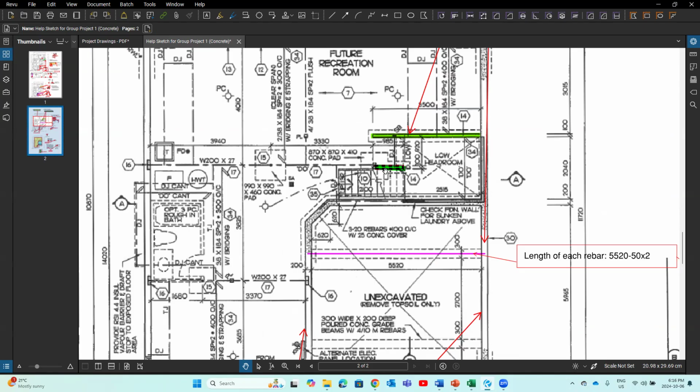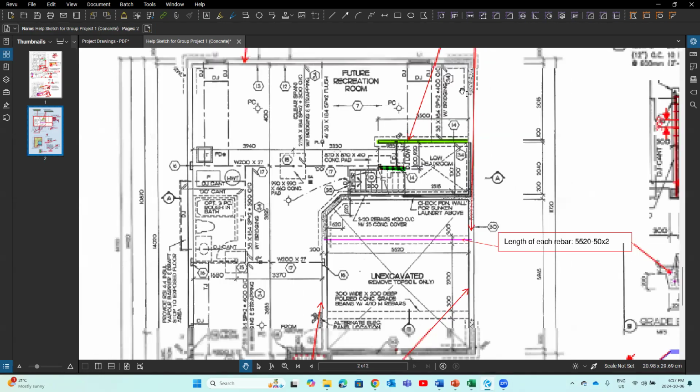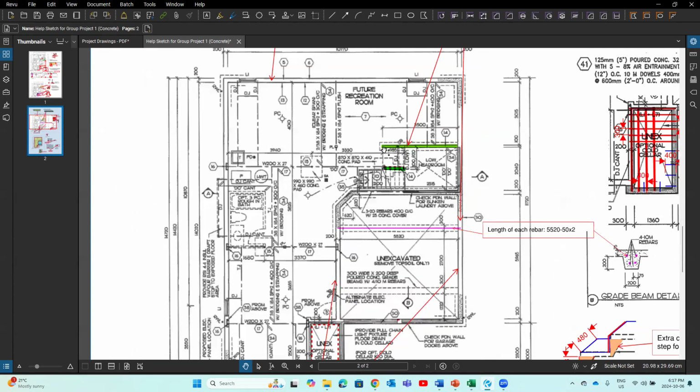That's a spacing of the anchor bolts, right? If we take the total length divided by that spacing, we don't have enough for this kind of situation, right? So what do we say? Each open end, we also add one extra anchor bolt in our estimate. That will give us enough anchor bolts. Okay, understand? So each corner, each open end, we add one anchor bolt extra.